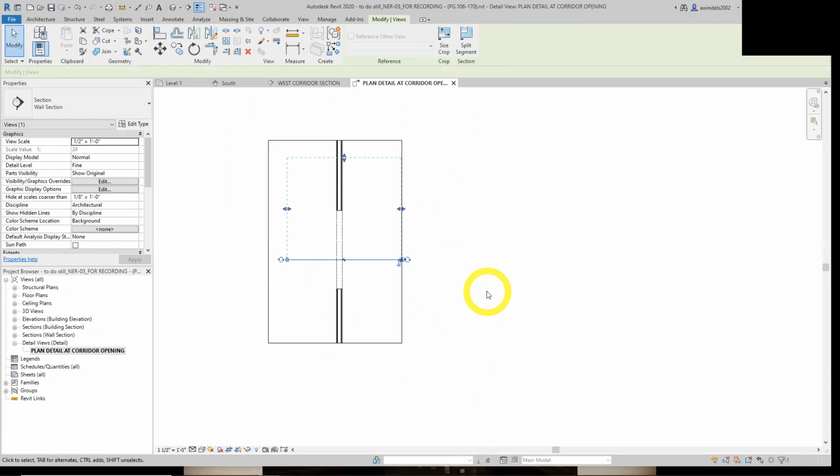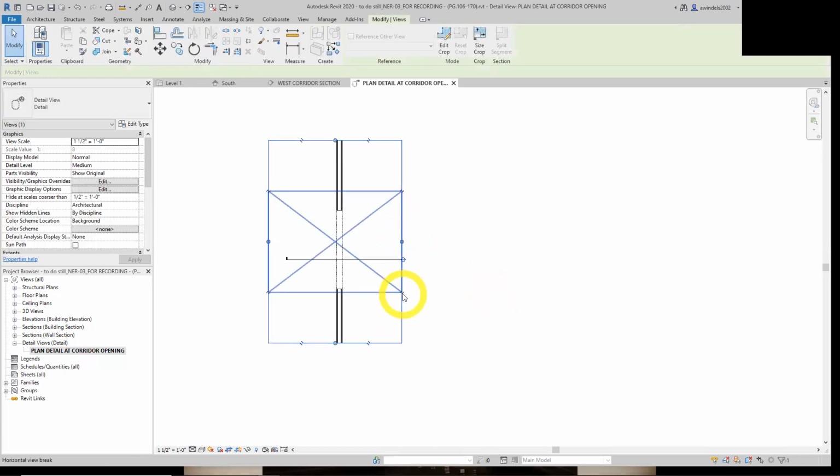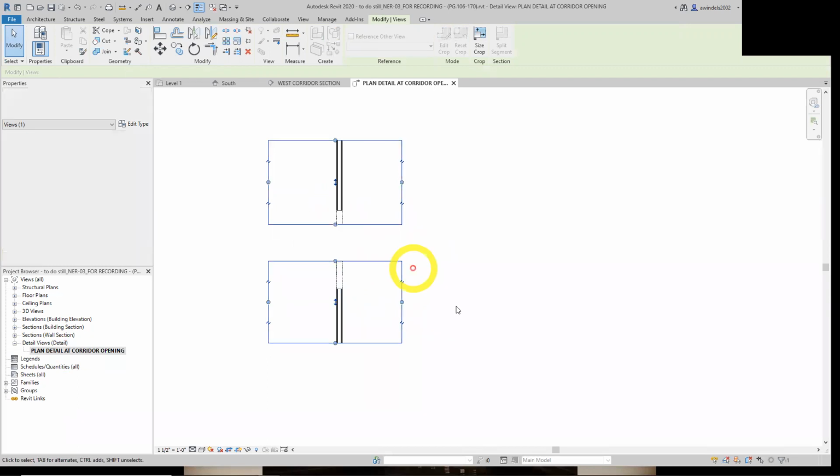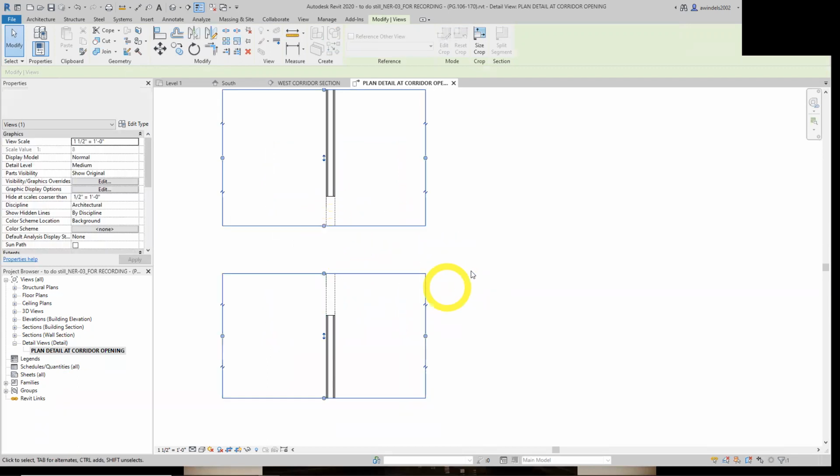And it's saying we're going to do some stuff. We can cut it in the middle. You can pick this view, choose to break out a piece of it like that. And it breaks it. You can still readjust to exactly where it is so it doesn't show the middle, makes a break in it.